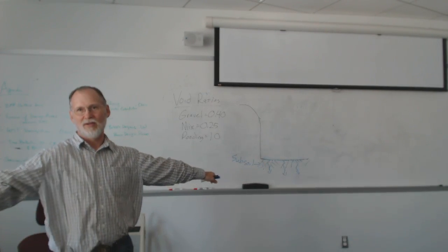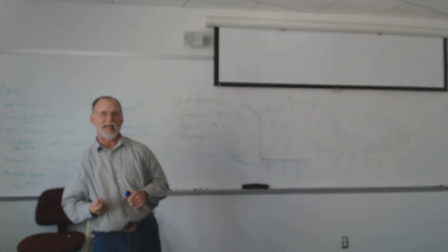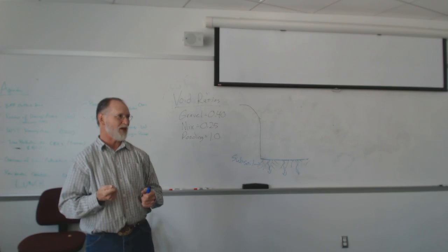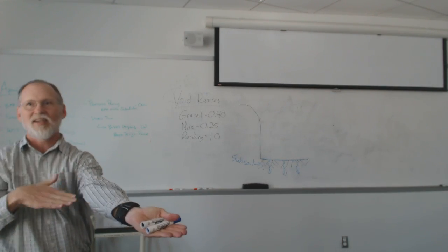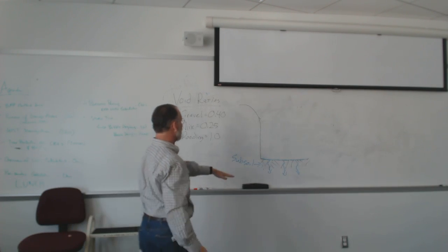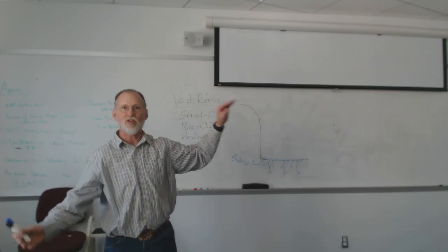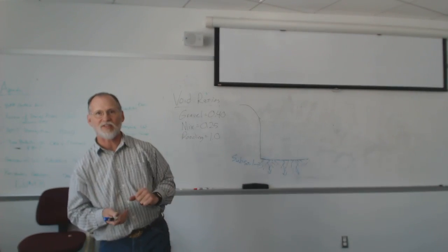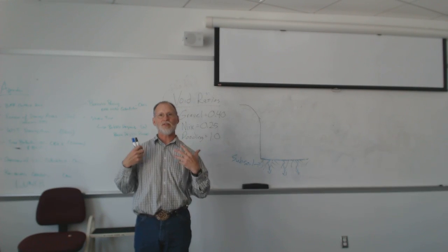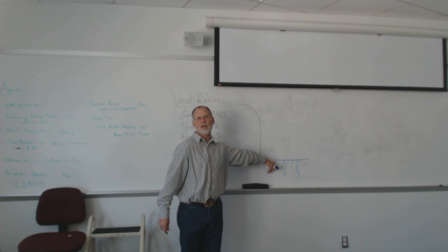It's beautiful. And it's horrible for a BMP, because if you have any clay in your soil, as we talked about when we did the infiltration test, if you have any clay and you smear it, you've basically sealed this off. You may as well lay a piece of plastic in the bottom for all the infiltration you get. So you did a great design, you picked the right plants, you designed the right thing, you did your infiltration test, and because they didn't know what they were doing, the person running the excavator just screwed up your entire rain garden right there.